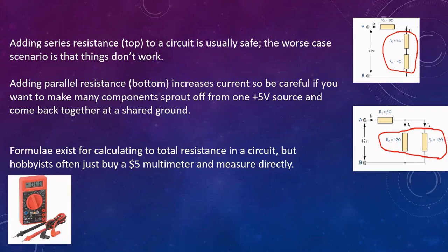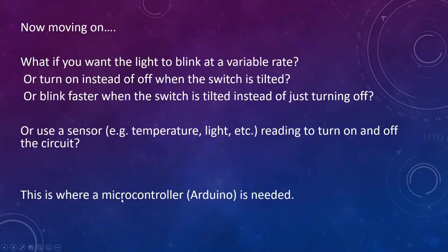So if you've got a resistor and you're not 100% sure if it is actually a 220 ohm resistor or if it's broken and doesn't do anything, you can use one of these multimeters to verify the resistance. So you don't need to read the label. If you've lost the label, you don't need to read the stripes on the component which tell you the resistance. You can just measure it directly. Anyways, that was just a side tangent, but important before we get into fancy computerized electronics.